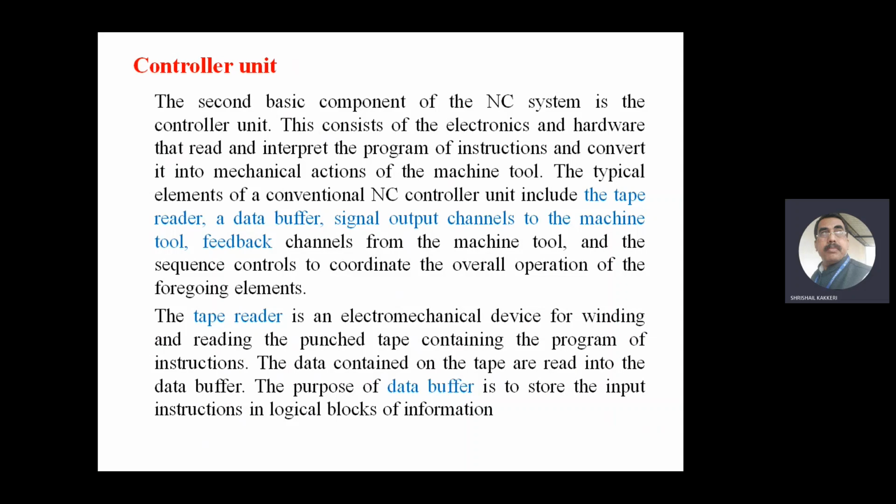The feedback system is one. In the robot also, for example, I wanted the robot hand to rotate by 30 degrees. I have given an input of 30 degrees. For this input of 30 degrees, as per the Newtonian method and DH representation, which I told you, to rotate it to 30 degrees, how many rotations I have to do at individual joints will be calculated. That is direct and inverse kinematics. Okay, and once after rotating, whether it has rotated 30 degrees or not, to understand it, at each and every joint there will be a feedback system, a drive.